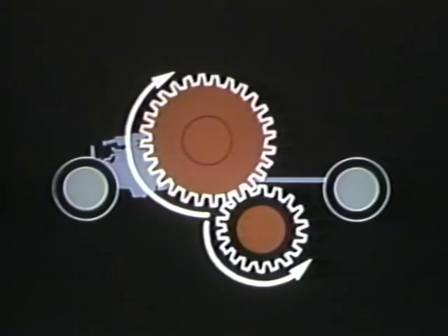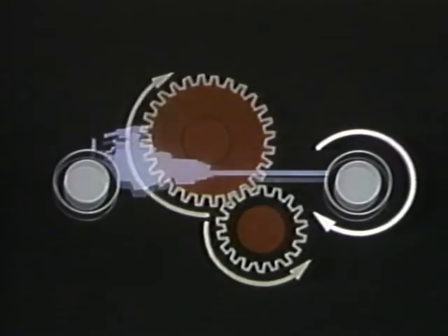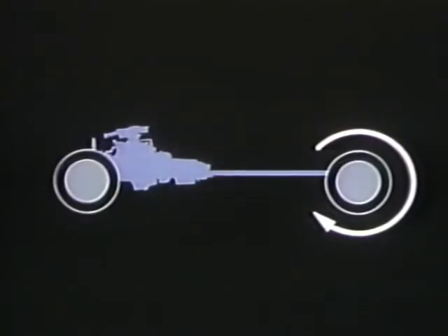The second mechanical function is providing the required gear reduction to smoothly move a vehicle from a dead stop up to cruising speed. The third and final mechanical function is changing the normal direction of rotation so that the vehicle can be moved in reverse.